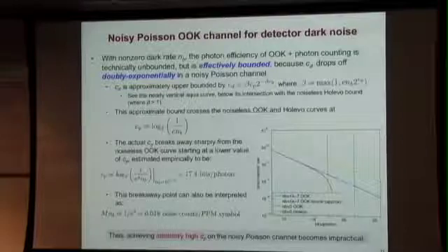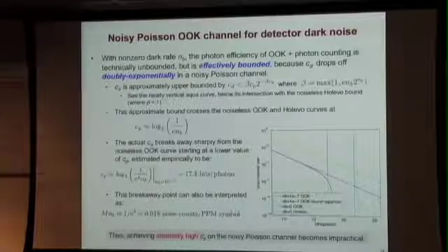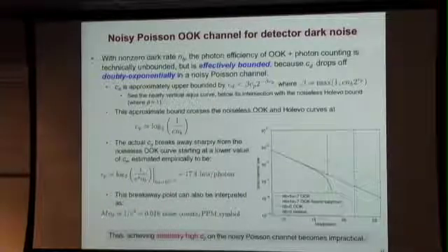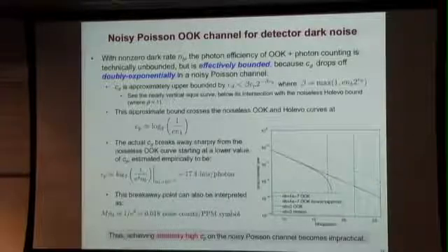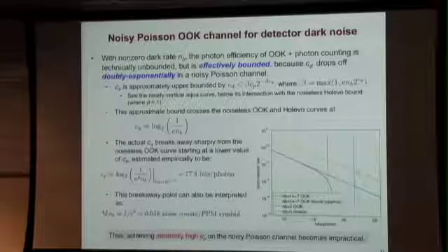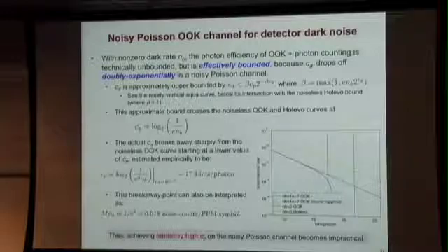So log of this value versus log of this value is the difference between that dotted line and that dotted line on this axis. And log of e cubed is about 4 bits. So somewhere in there is the best analytic model we have for how quickly dark current or background noise will start to kill you. And translating, remember the optimum M value of PPM. If you plug in the optimum PPM and multiply it by the nb that fits into this formula, basically you need to have this product, because M is basically proportional to 2 to the CP, remember.